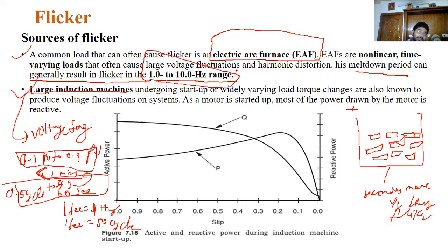At the same time, in the voltage fluctuations, a voltage sag will also lead to an interruption. We are unable to identify that by the human eye. But whenever a flicker happens in the system, less than 0.1 pu, that will be maintained at a 1 to 10 Hz frequency. So the human eye is able to identify that, and we can call it a flicker.